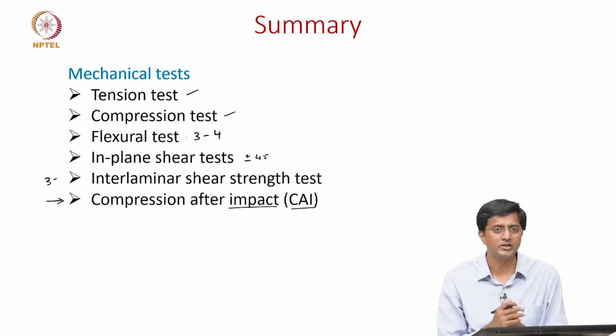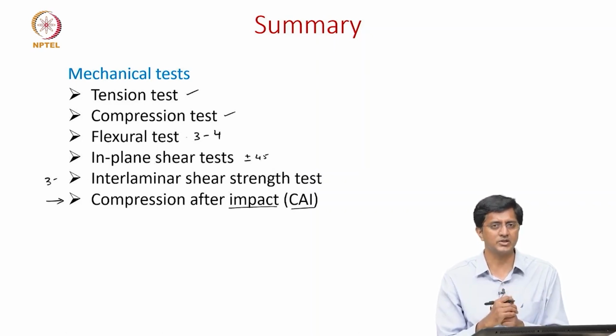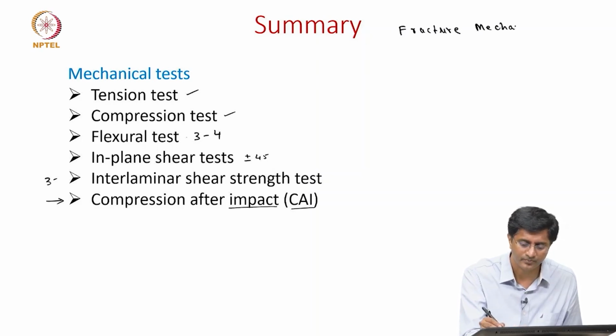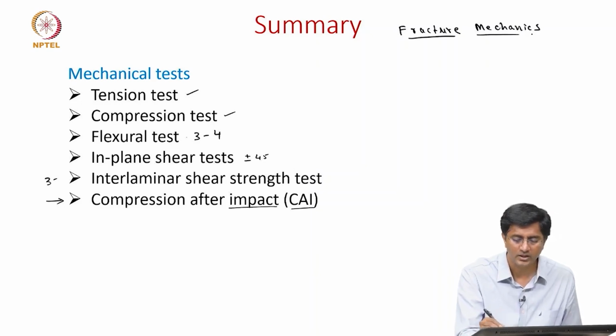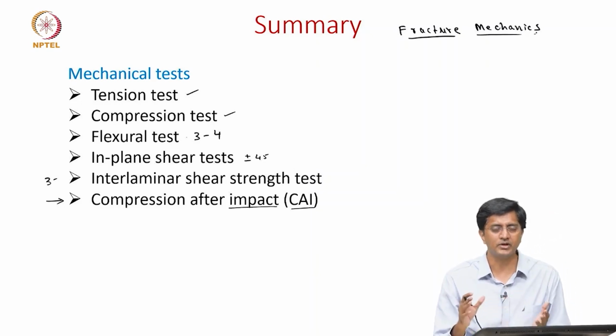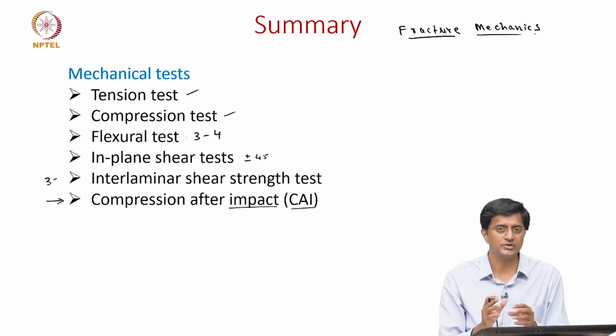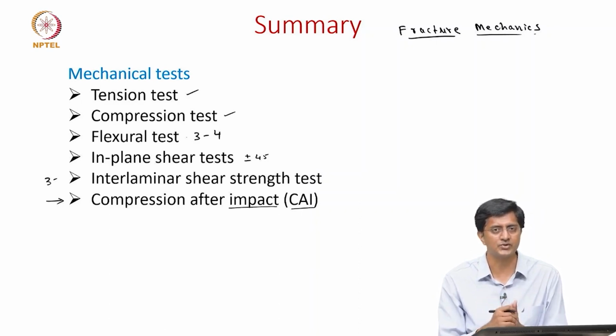And I need to make this very important point that the approach we are following here is the mechanics of materials approach, but there is another approach called the fracture mechanics approach to analyze failures. In that again there are several different test methods available to first look at the fracture resistance in opening mode and the fracture resistance in shear modes, as well as, if there are both opening and shear modes, what specimens one should use. But that's a very advanced topic which we are not focusing on, at least in this introductory course.